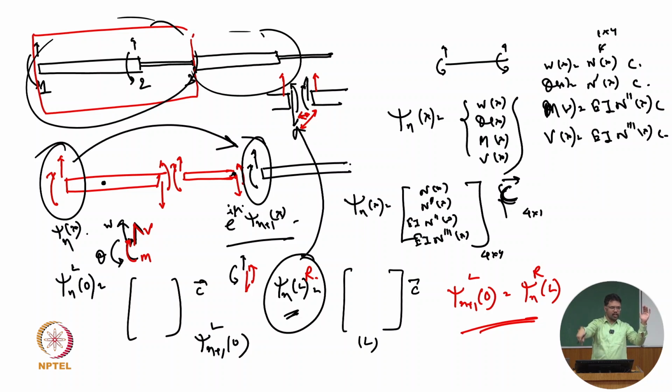In the right side, what happened? Cutting, shear force is going downward, and bending moment is anti-clockwise. Now at that junction, what happened? Left side, bending moment is clockwise, and right side bending moment is anti-clockwise. So that clockwise bending moment and anti-clockwise bending moment at that same location are balancing each other. And shear force is also doing the same thing, upward and downward. So at that junction, they are equal and they are balancing each other.